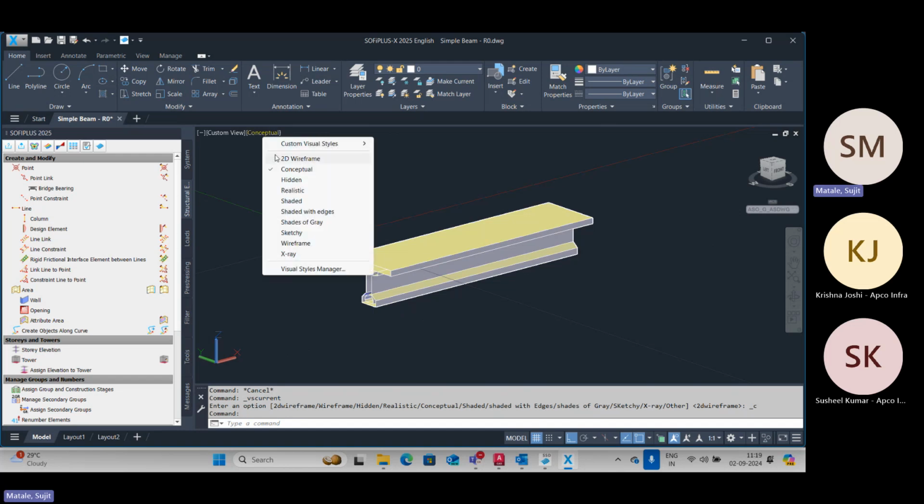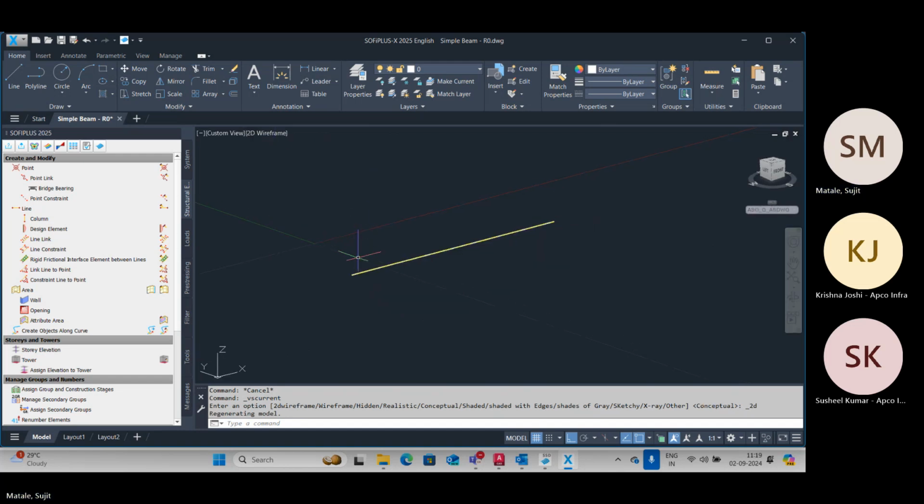Now, our next step is, if it was any other program, you would have to first define two nodes. Then you would have to define the element in between. But in Sofistik, it is not that. In Sofistik, you can directly draw a line, because here in Sofistik Plus, it is still at the structural elements level. So it is one element now. But when you export it, at that time it will break this particular element into smaller pieces of whatever 1 meter length, 0.5 meter length, whatever the automation options are. And it will create nodes right from start to end and many nodes in between.